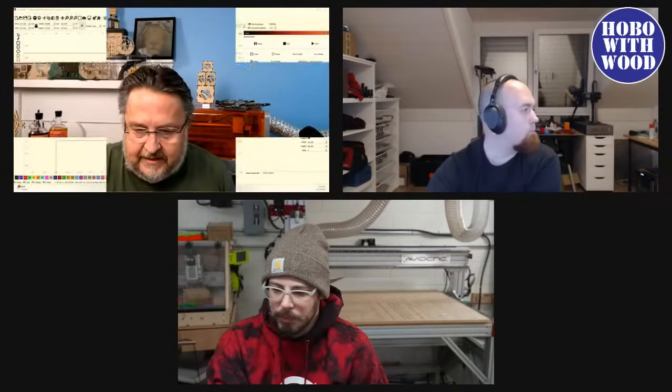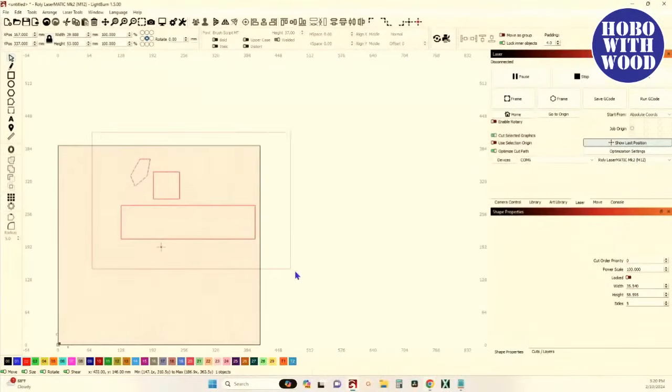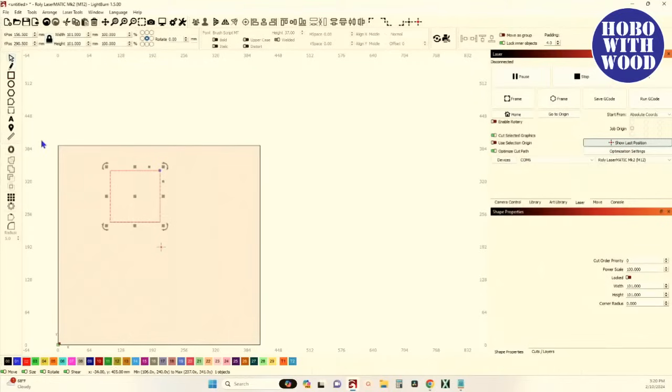So in fact, I'm going to switch back again and we'll make that full screen. So the radius tool, now that tool is the rectangle tool, but if you hold shift, you draw a square. And this threw me a bit of a curve at first, because when I read the instructions, it said this draggable radius tool is for rectangles only. And I'm like, wait a minute. It won't work with squares, but it does work with squares.